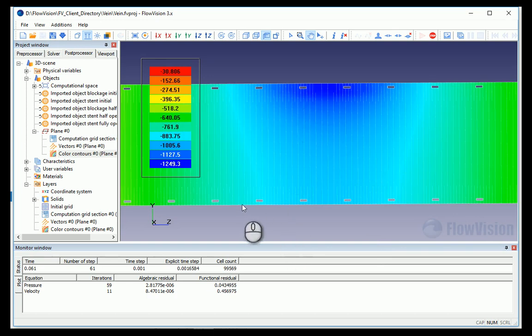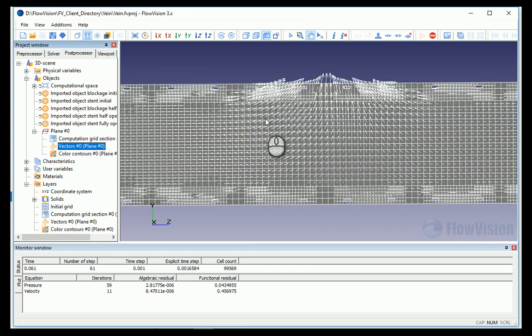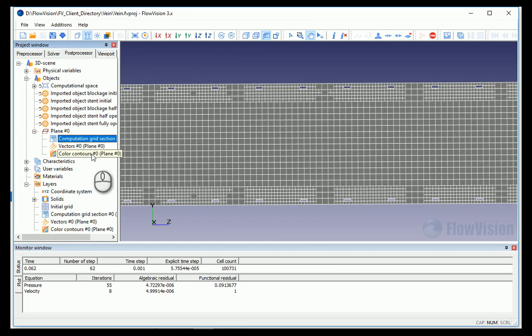Yeah, here as you see, automatically the body is changed and the flow is superposed. Of course, the more stages you use, the more accuracy you will have in your calculations. That's obvious. So here, for example, in this case, the flow is trying to adapt to the new geometry. So this is also, as you see, we have the adaptations used here.